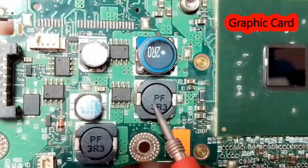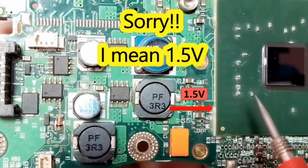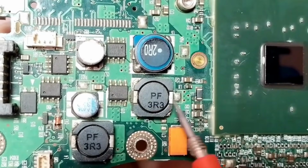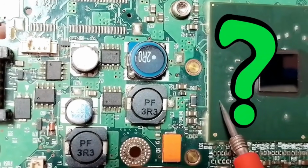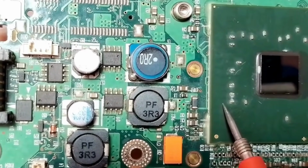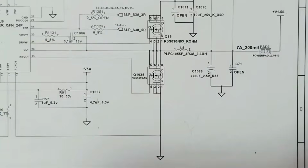This is the graphic card here, near it. The 1.5 volt comes from this inductor directly to the graphic card. So the graphic card could also be the shorted component, because if there is any short circuit in the graphic card, we will get this inductor shorted because there is a direct connection between them.